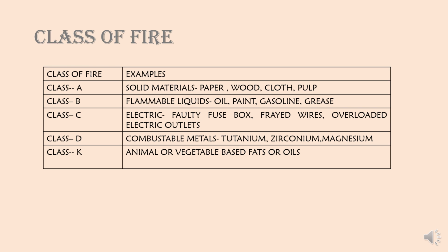The Class D fire involves exotic metals that are combustible, like titanium, zirconium, magnesium, sodium, etc. This requires special agents such as dry powders and special application techniques.